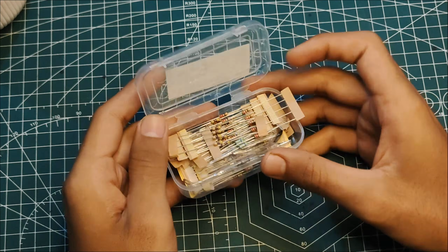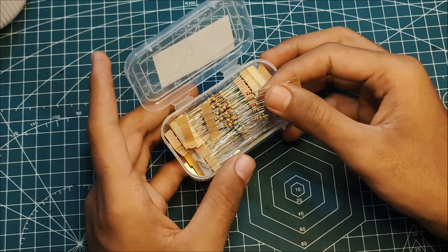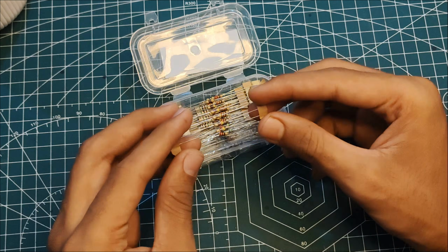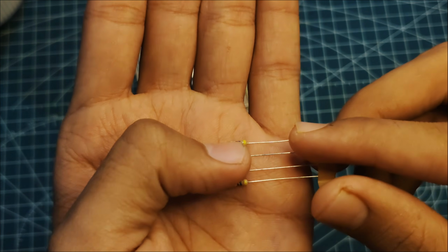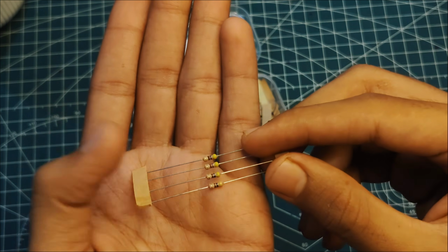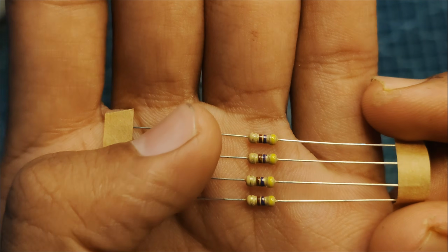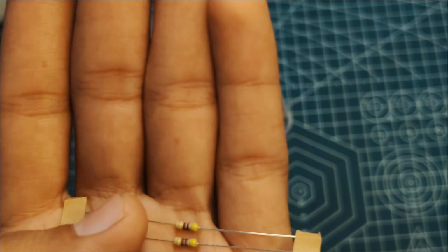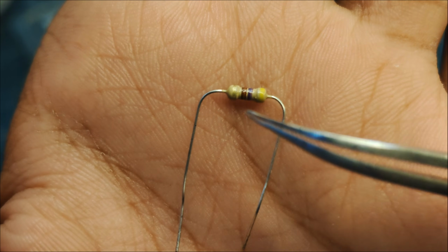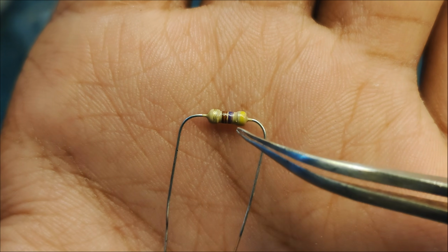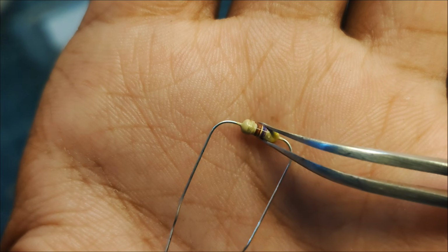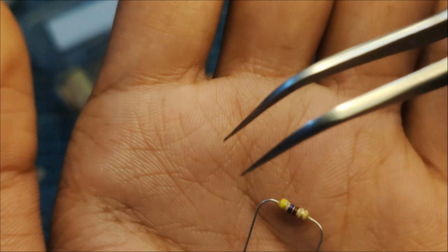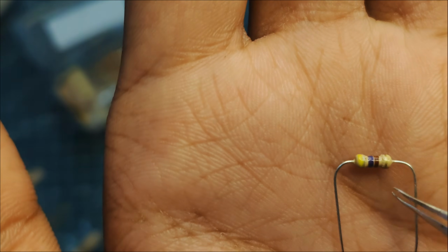Now let's understand the basic application of a resistor, what exactly a resistor is, and how we can calculate the value of a resistor based on the color code. As I already told you, all the characteristics and how you can do that using the colors on top of this resistor. You can see there are color bands on top of it, and if you take a very close look, the first color here is gold, so we need to put it on the right side. So always try to put silver and gold on the right side, and then try to read it out.